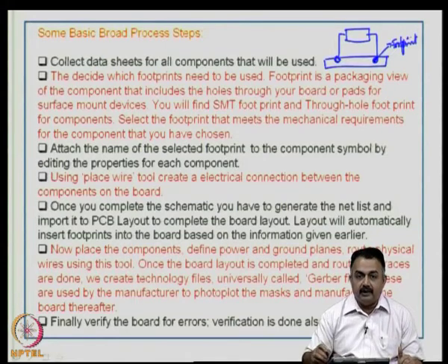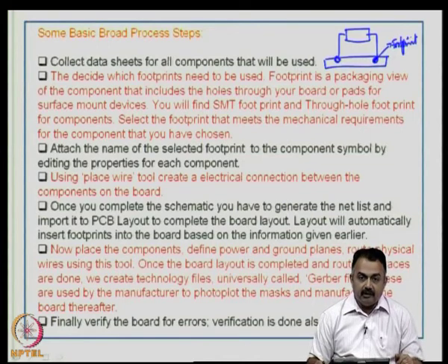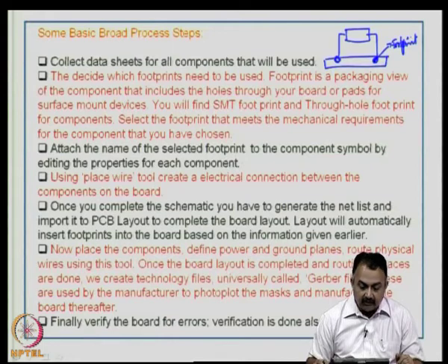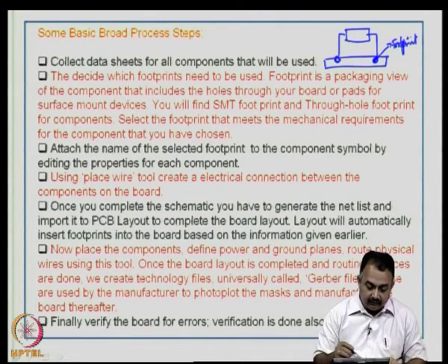So, you will have footprints for every pin in every package. So, you will find SMT footprint separately, through hole footprint separately in your library, package library. Select the footprint that needs to be used and that meets the mechanical requirements correctly for the component that you have chosen. Okay. So, these are the two important steps.